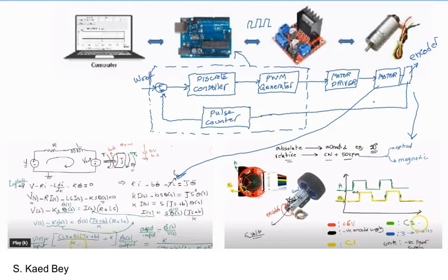The number of pulses is normally the number of signals generated by the Hall effect multiplied by the gearing ratio of the motor, and that will tell you the real rounds per minute of the motor. It's recommended you find this out using the datasheet, but I also recommend you double check this experimentally, especially if you are in doubt about the motor part number or you expect it has the wrong label on it.